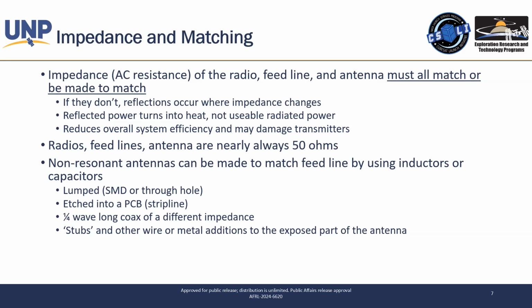And it's important that in a communication system, your components are all impedance matched. The reason you do that is because if you have a mismatched impedance, you'll get what's called a reflection. And that reflection back makes it so your network doesn't work as well. In fact, it can completely stop it from working altogether. So it's something critical you need to be aware of. Most of the time, the impedance that we baseline is 50 ohms.